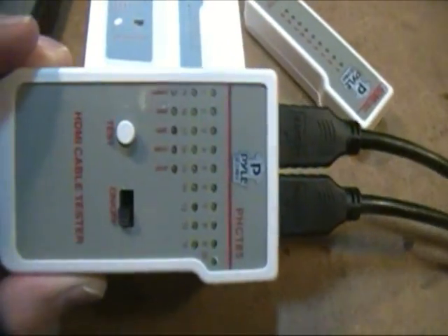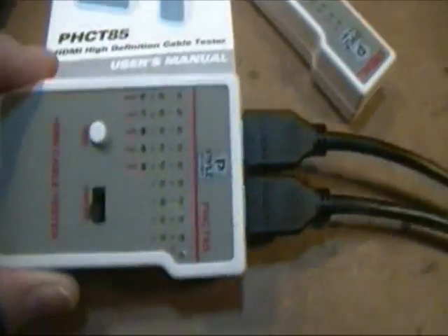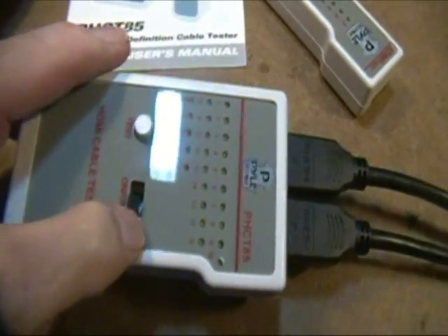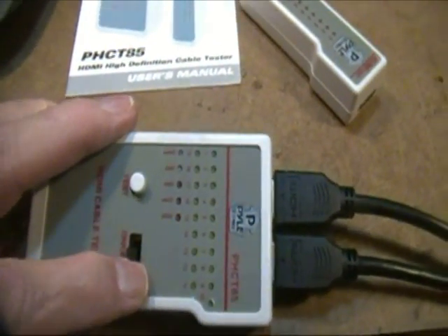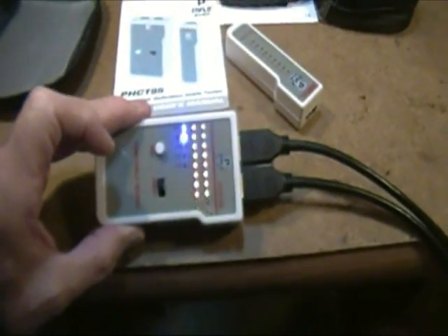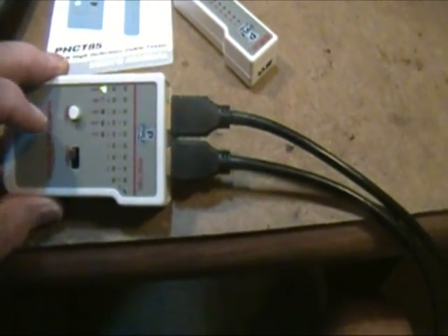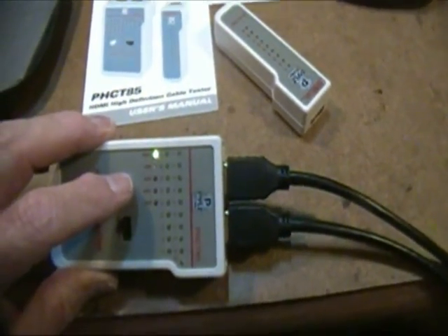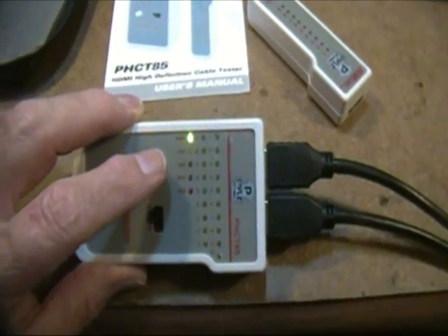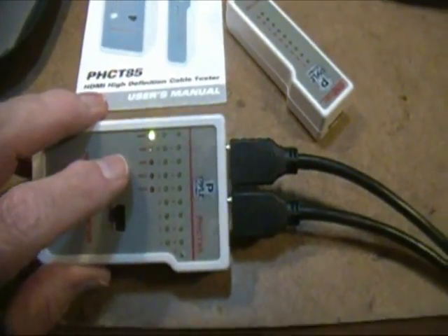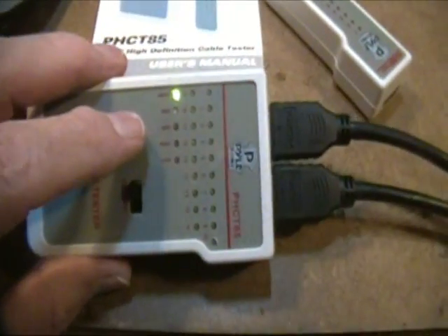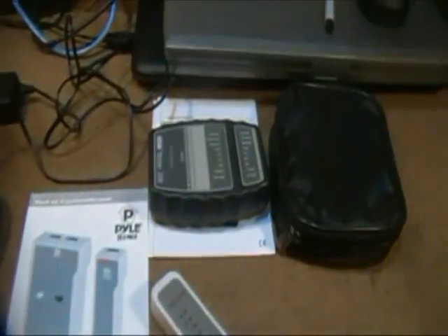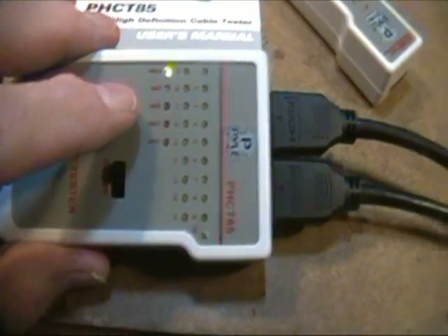I've hooked up the HDMI cable to this tester, and right now I've left the remote out of the picture. Unlike this HDMI tester or cable tester here, this one has an on-off switch. When you turn it on, it performs a test. And you see it indicates that all of the lines are working. Now, the difference is this unit is actually doing a dynamic test. That is, it's actually changing signals on each of those wires and making sure that they come through independently. This one, as far as I can tell, just uses a DC signal. And so I think this one will do a little bit better job of testing the cable, although I don't really think that either of them claim that they will verify how high a speed your cable will work.